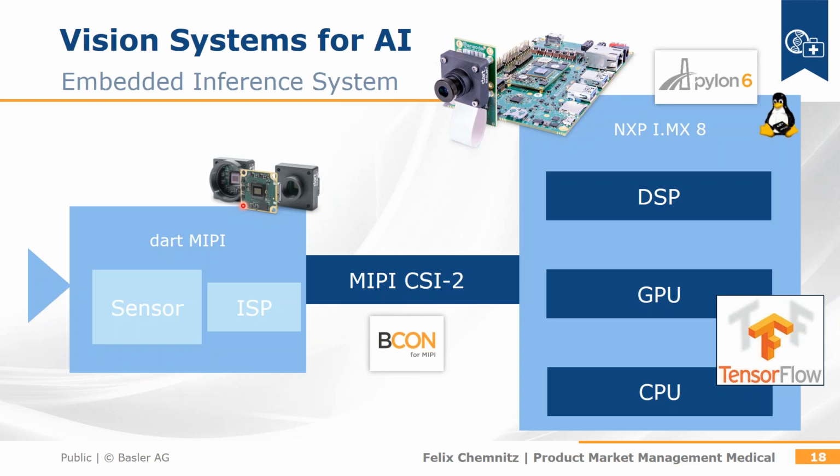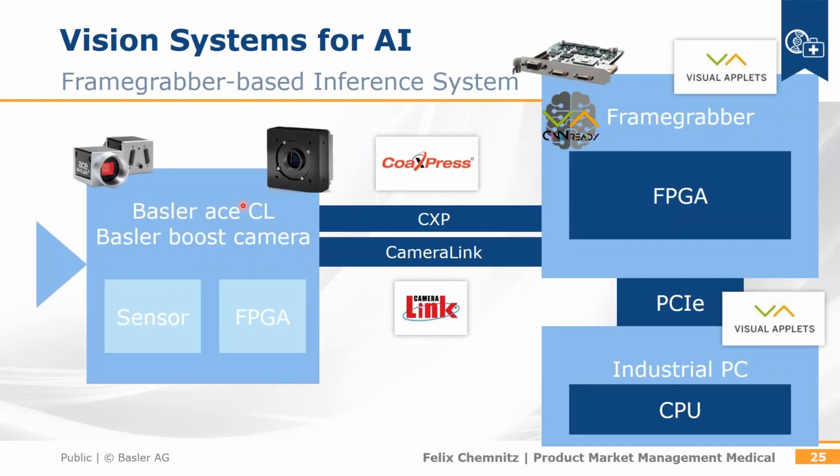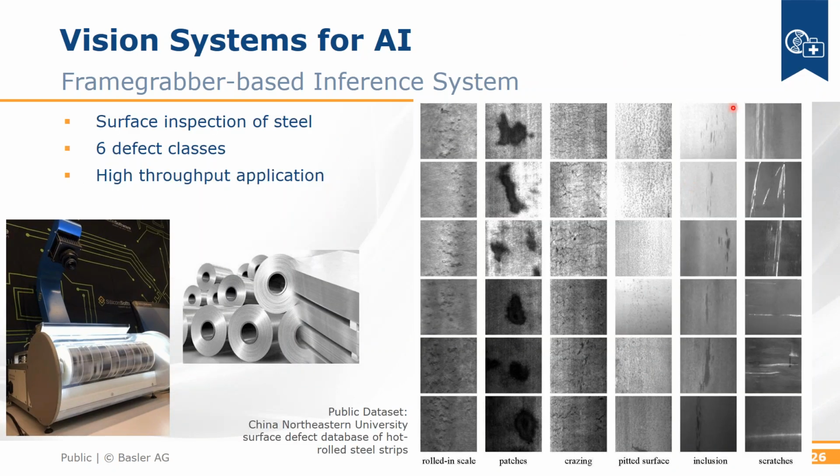Is it possible to buy a system with a finished inference from Basler? With a finished inference, yeah, there are two possibilities. We provide this for the frame grabber based systems. One is trained and ready inference directly running on the FPGA, but the customer needs to provide us with the images and the labeled images to train the network.